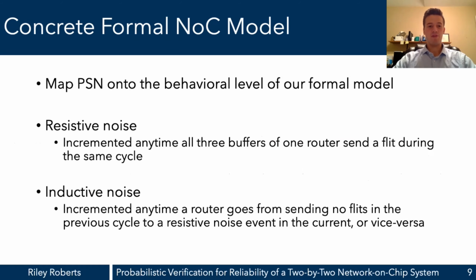For resistive noise, we incremented a variable anytime all 3 buffers of one router send a flit during the same cycle, which corresponds to high router activity. Similarly, for inductive noise, we increment a variable anytime a router goes from sending no flits in one cycle to a resistive noise event in the next cycle, or vice versa, indicating a large change in router activity.